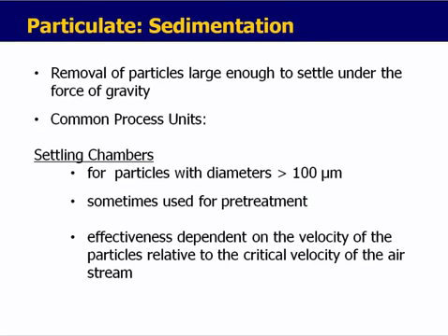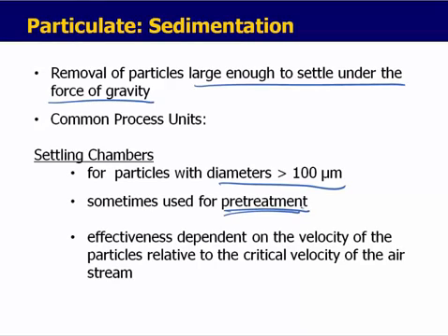Sedimentation is used to remove particles that are large enough to settle under the force of gravity. This is appropriate for particles greater than 100 microns in diameter. It is often used as a pretreatment because it is fairly inexpensive. The effectiveness of this is dependent on the velocity of the particles relative to the critical velocity of the airstream.